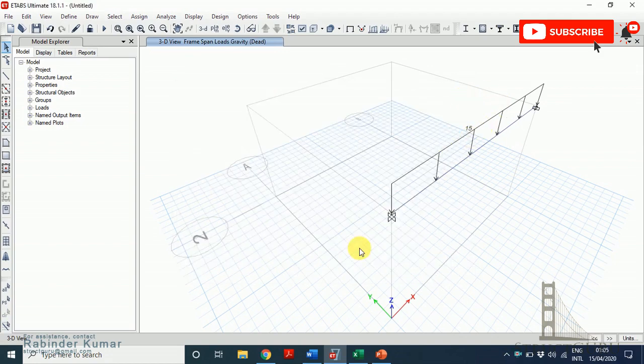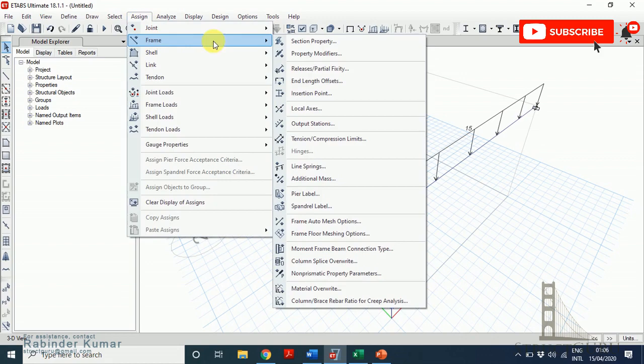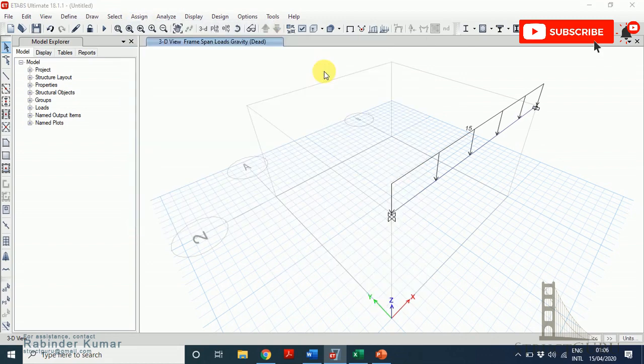First let me tell you, to assign the release option, there can be three cases. First is no release, that means both ends are fixed. Second is making a pin connection. And third option is partial release, that means you have to reduce the stiffness of the support by some percentage. Let me tell you where you will find this option. Go to the assign menu, frame, and then release or partial fixity.